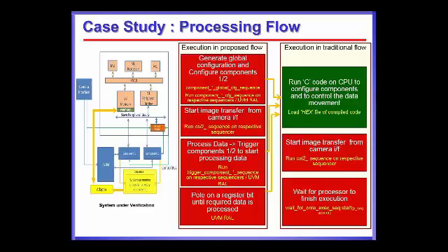So what we did here is that we are running sequences which are UVM sequences, and then converting those atomic transactions initiated by those sequences into an instruction, and that is still being executed by the processor. And in order to do the same thing in the traditional flow, we just have to write an equivalent C program for steps 1, 3, and 4, right? So we could actually write C programs, just compile them, put the hex in the memory, and the traditional flow is being run.